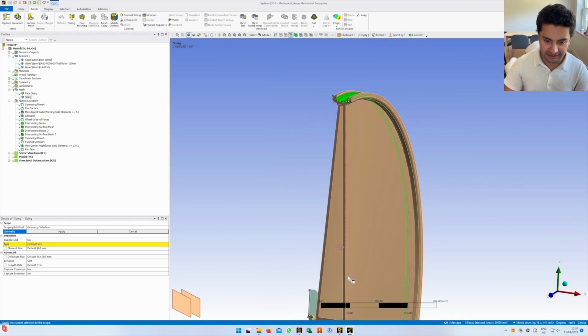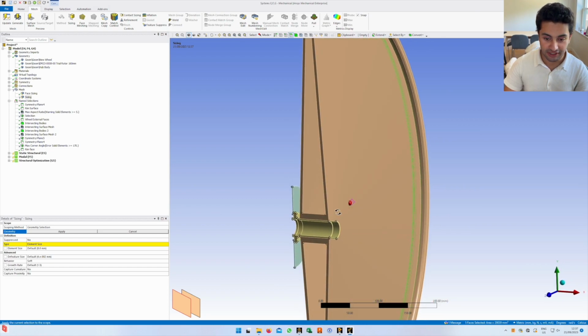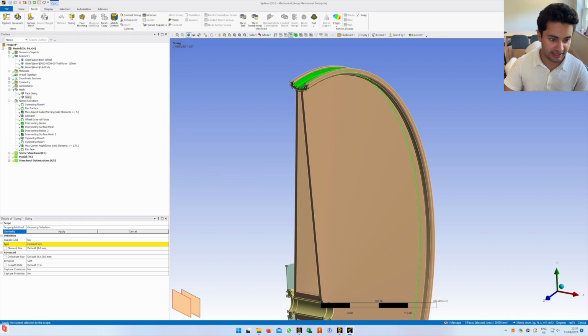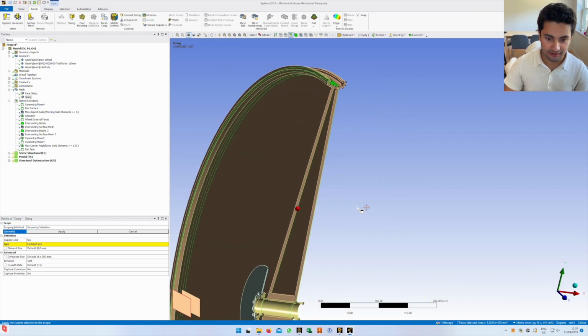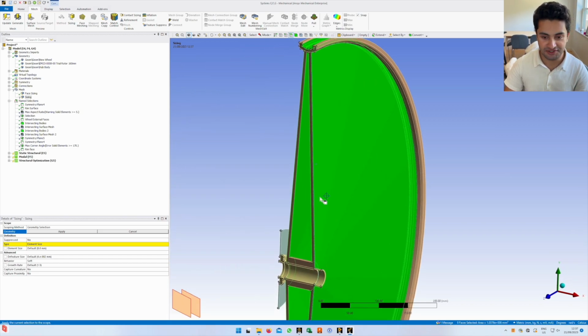Here, really simple flat surfaces, which do not take so much of the load. We can save on computational resources and just select these big faces and put those up to a mesh size of 5mm maybe, because we don't need to capture so much detail there. So that's the sort of stuff you would do with the sizing.